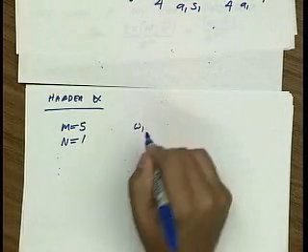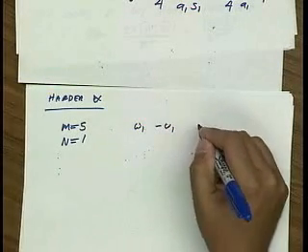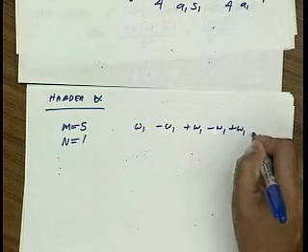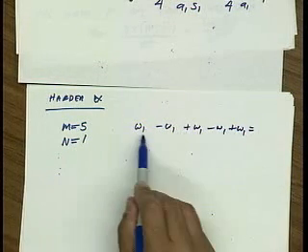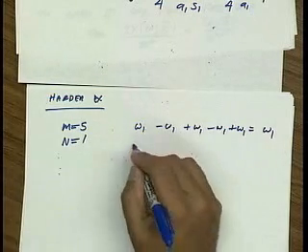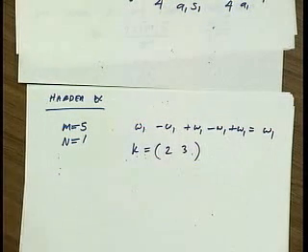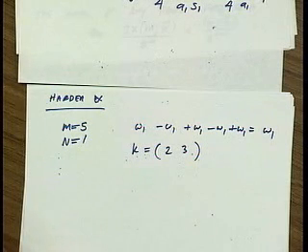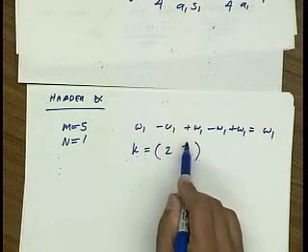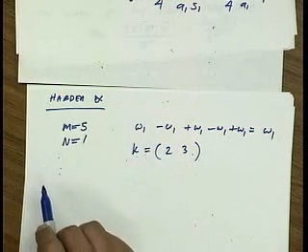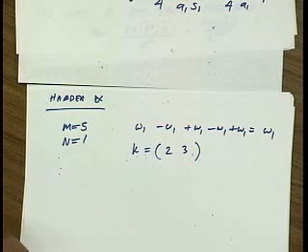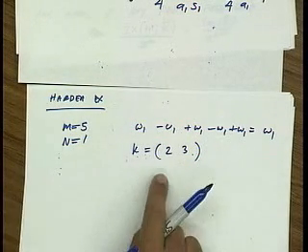And the observation here is that if I have basically 5 tones, then as long as I get a cancellation, so I have 3 omega 1s and 2 negative, I end up with a net omega 1. So any k vector like this will produce a tone at omega 1, right? So remember, 3 plus 2 is 5. It's a fifth order nonlinearity. And as long as I get 3 omega 1s and 2 minus omega 1s, I get a tone at omega 1. You can, of course, do the complex conjugate, 3, 2, get the same answer, right? Everybody see where this comes from?